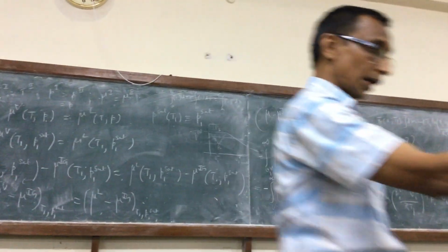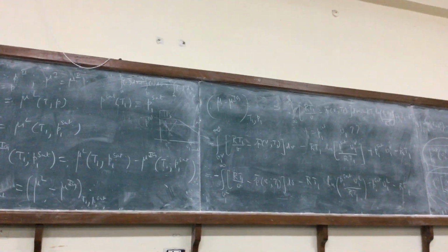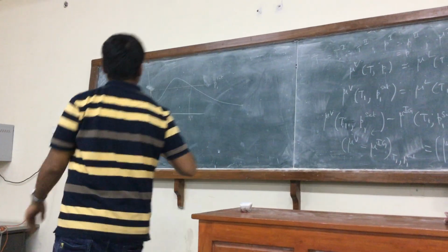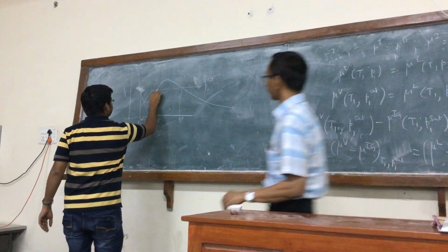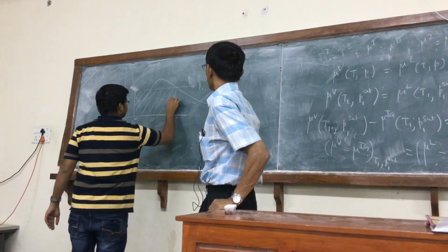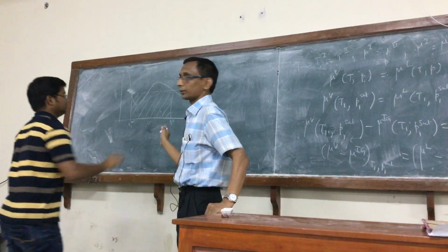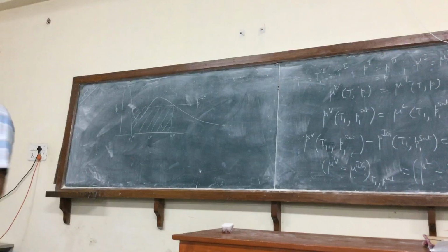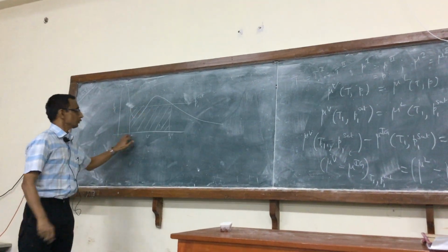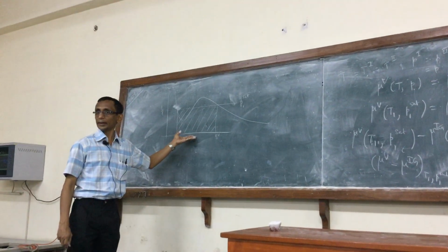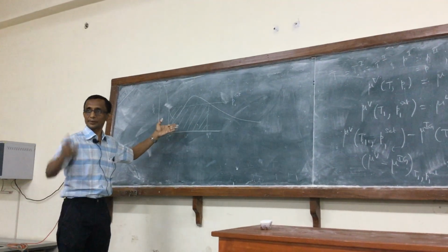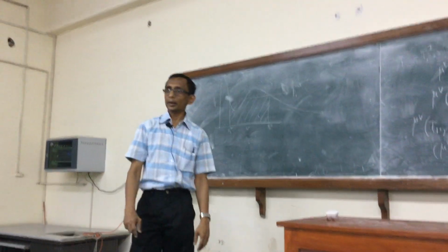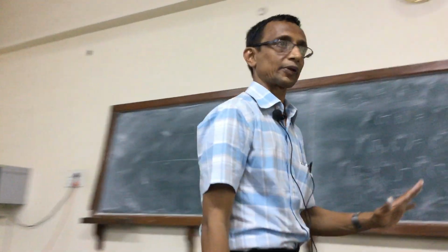Can you mark the area on the figure? V1 sat times (V1V minus V1L). Mark it. Very good. Easy to do that, right? It's a rectangle: V1 sat times (V1V minus V1L). That's the area of the rectangle. It is clearly marked, right? So that is the equal area, the area represented by the first term.